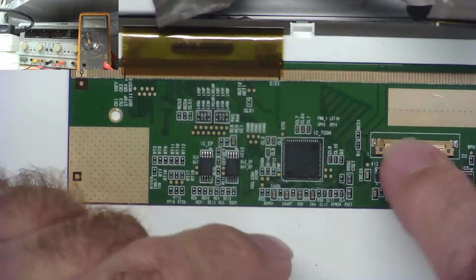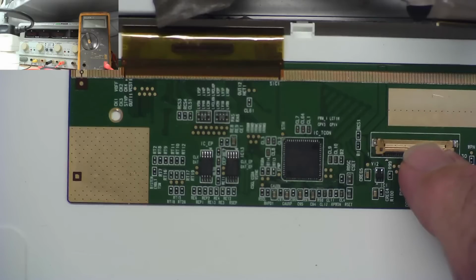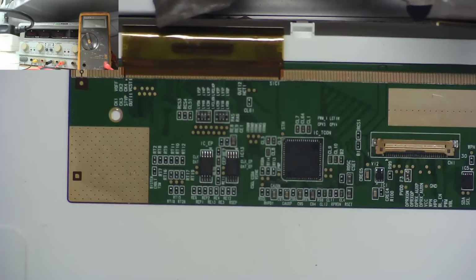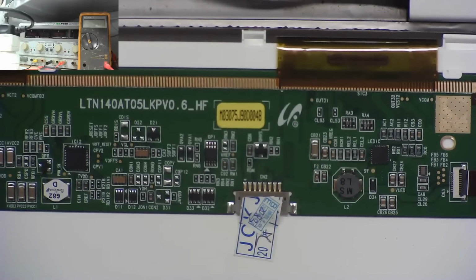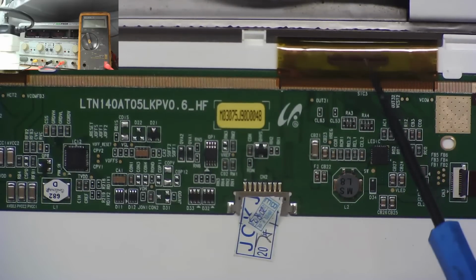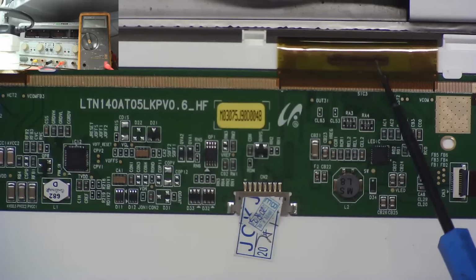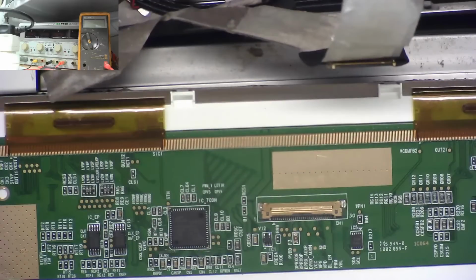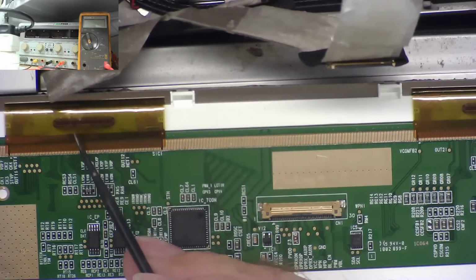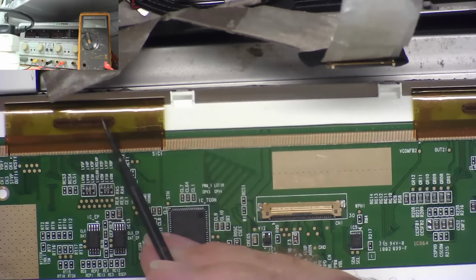So the data will come in here, LVDS, low voltage differential signal, and that data will be processed by this board, and going down these three ribbons effectively is going to be the video. You can possibly just see actually that there's something inside here. Yeah, that's a chip, and they're called chip on flex, COF, and these quite often fail on LED and LCD TVs. You can see that one probably quite clearly, and these sometimes fail, and that's what gives you vertical lines